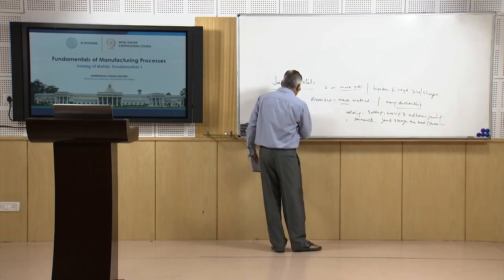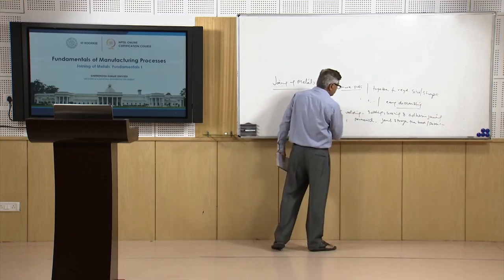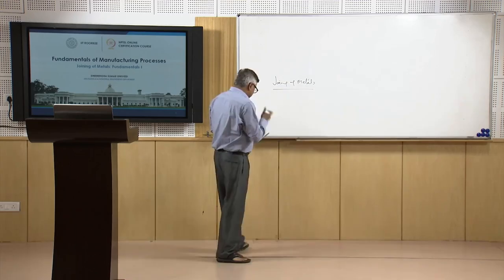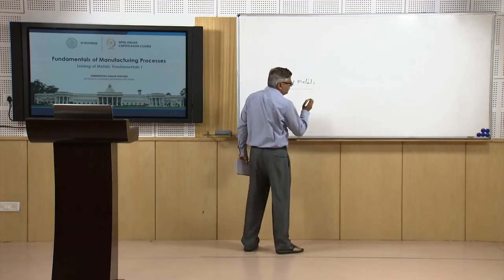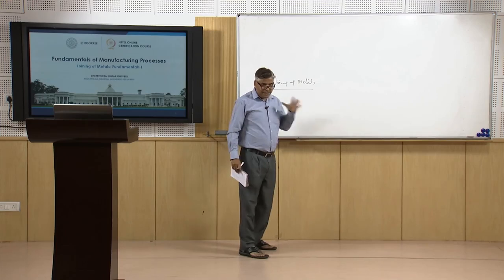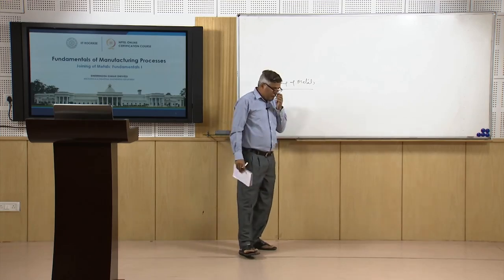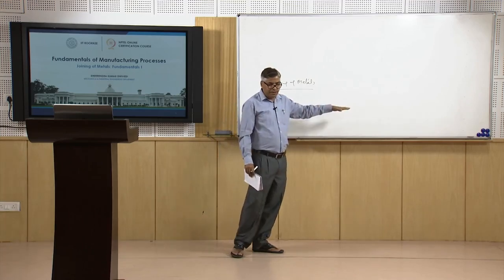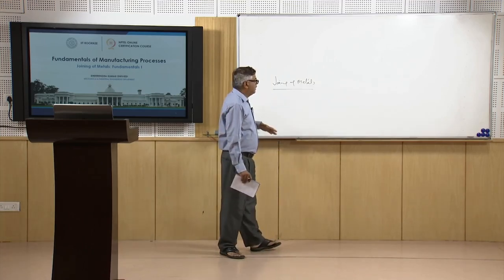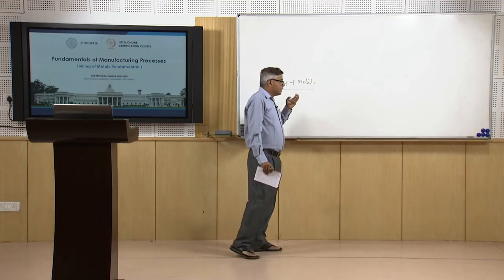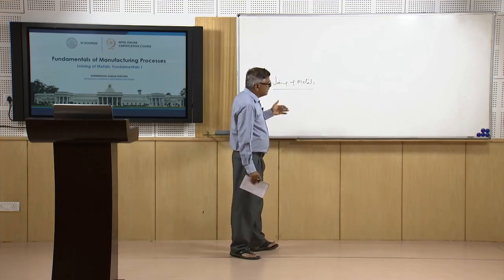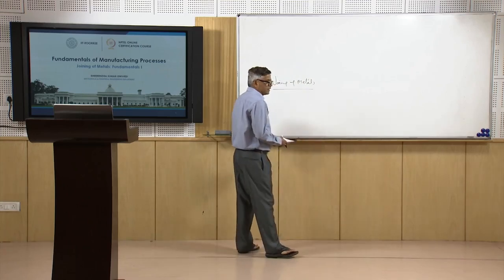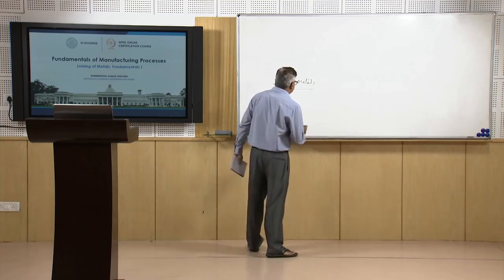So, basically we will be focusing on the joining techniques used for metal joining. As I have mentioned, the joint is permanent in nature, which is produced mostly in joining processes like welding, brazing, soldering and adhesive bonding, and suitable selection of the filler metal can also lead to a joint which may be even stronger than the base and parent metal.